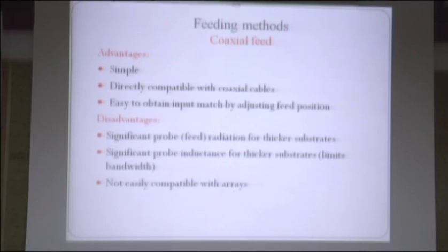It is not easily compatible with arrays. If we design arrays, then it is not compatible because we are not connecting more than one coaxial cable with the patches. So for this purpose we use microstrip lines for connecting patches with input signals.